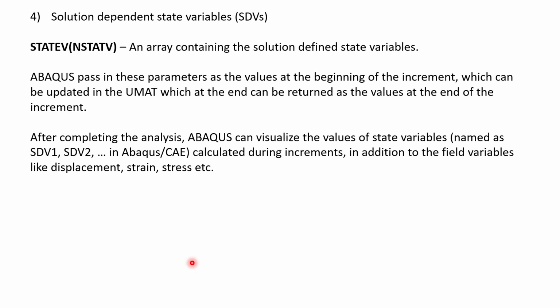The last type of variables is solution dependent state variables. STATEV is the name of the variable. NSTATV refers to the number of state variables which we are defining. STATEV is nothing but an array containing the solution dependent state variables. Similar to other variables, ABAQUS passes in these parameters at the beginning of the time increment. These have to be updated in the UMAT and then returned as the values at the end of the increment.